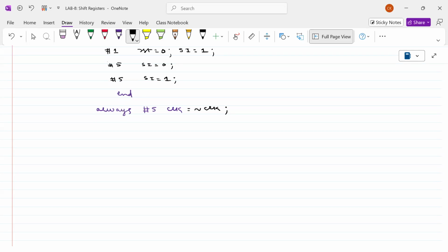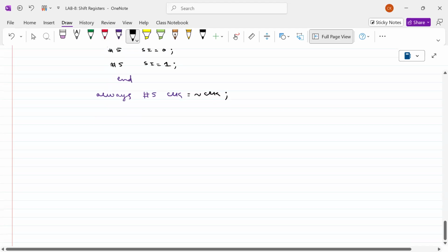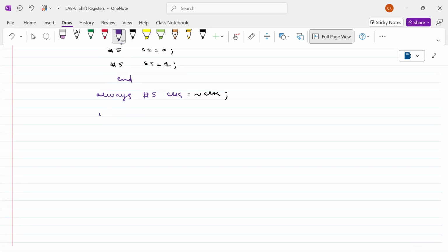When can we stop the simulation? For example, 4 clock pulses, that will be 0, right? So all the serial in data will be transferred to the serial output side. The 4 clock pulses are required, so how much is this value? For example, 50. Okay, it's more actually. We can stop the simulation at 50 nanoseconds. Initial, at 50 nanoseconds, $stop.